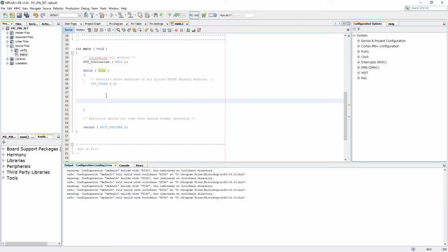In this video, like we said, we're gonna just set the state to high or low. So upon programming, the state that's gonna be permanent. LED is not gonna be blinking. The port is gonna stay as we direct it to be. How can we do that? Is by using some of the files that have been generated through our code from MPLAB Harmony.